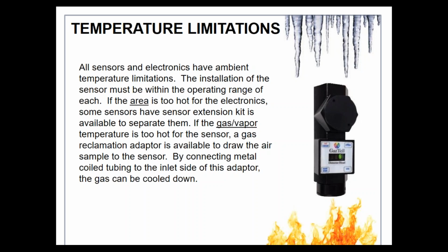You can put a catalytic bead in there, but not the IR. If you get down to, let's say, 60 degrees C, you can't put an electrochemical cell in that environment. It'll boil the electrolyte off. So a lot of the decision making on where you place the sensor is dependent on the capability of that technology, also that detector head.